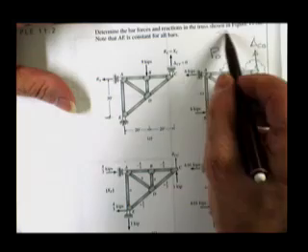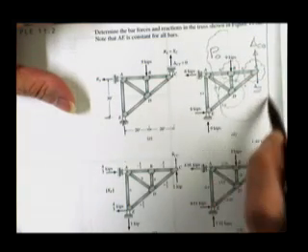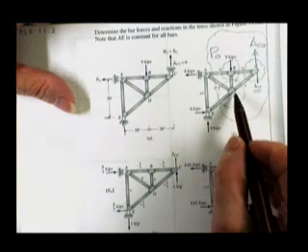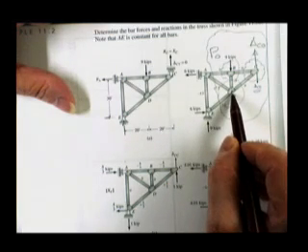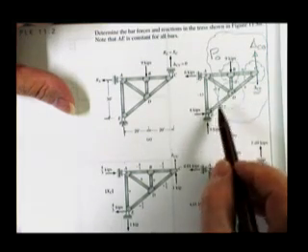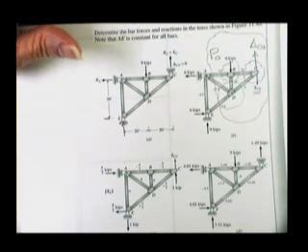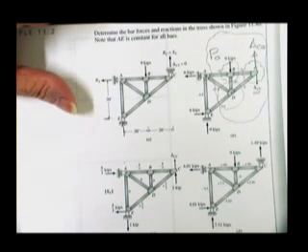If you would rather, you could do method of sections. That would probably be a good section. You could solve for the force in this member by summing moments about D. You could solve for the force in this member by summing moments about A. Your choice. Anything that you find straightforward and simple to do probably is the best thing that you do.